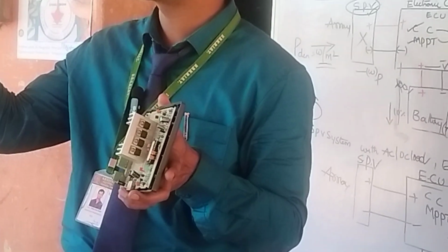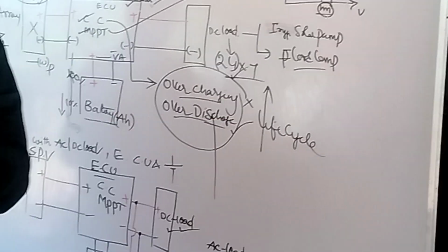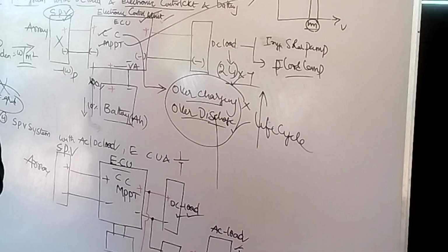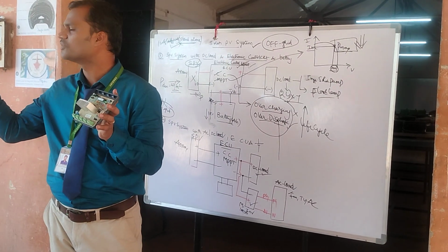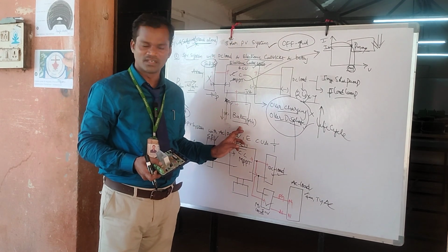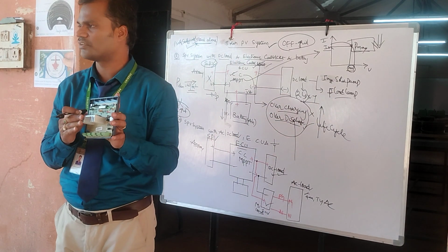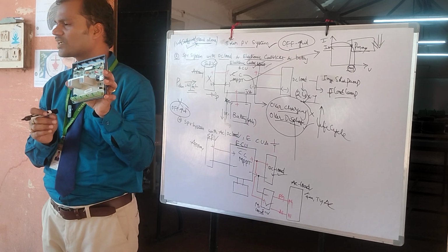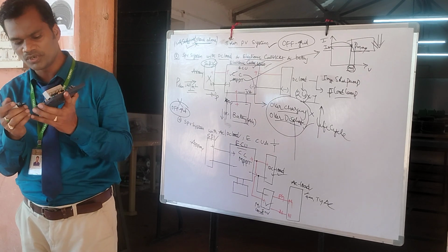The problem is only with DC load. So I am going to have an AC load with the help of a small inverter which is called a micro inverter. By using this micro inverter, the output may be phase and neutral. We can connect an AC fan, AC tubelight or AC appliances like a water purifier, everything. So these sort of systems are called off-grid types. Off-grid means there is no grid in that location. There is no availability of electrification in that location. Then you can use this configuration and supply power to those people. So now this is about the off-grid system. Now we will discuss the on-grid system. How many on-grid classifications are there? And we will try to perform an experiment on the off-grid system and on-grid system.